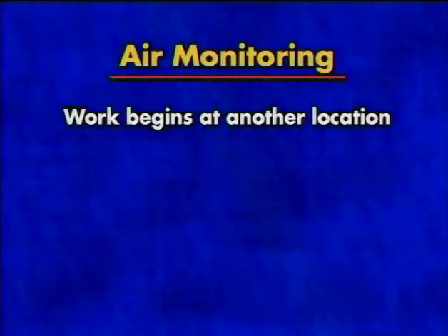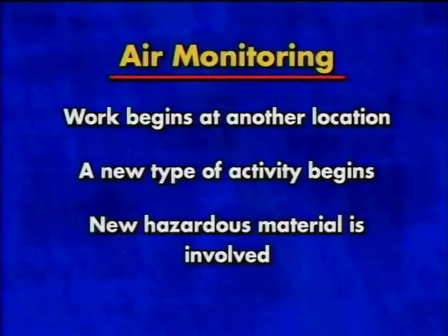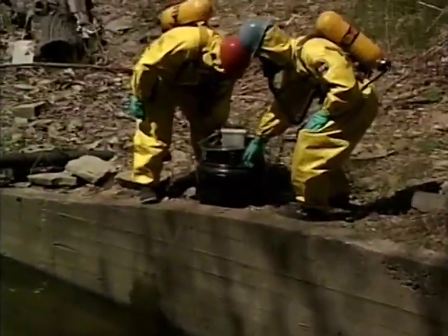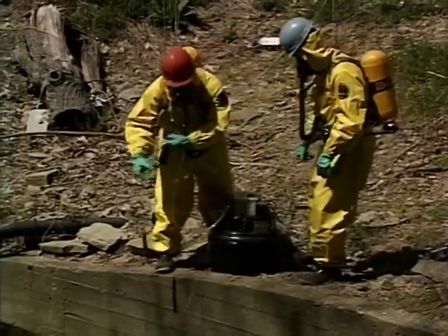Air monitoring will also take place anytime work begins at another location in the site, a new type of activity begins, or a new hazardous material is involved. Monitoring is also required whenever workers are handling leaking drums or containers, or work in areas with obvious liquid contamination, such as a spill or contaminated water.